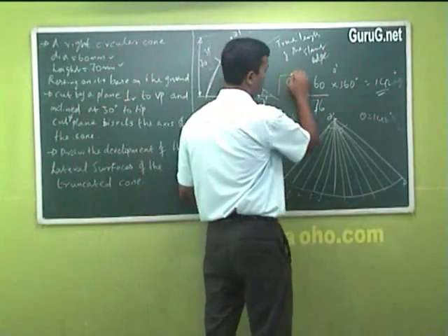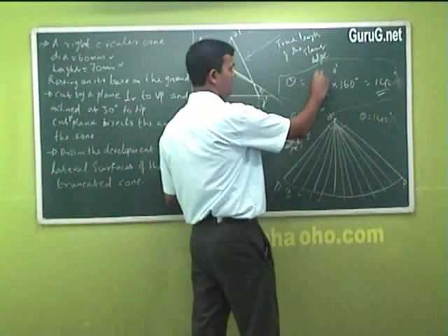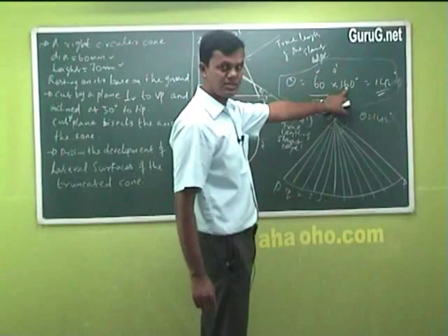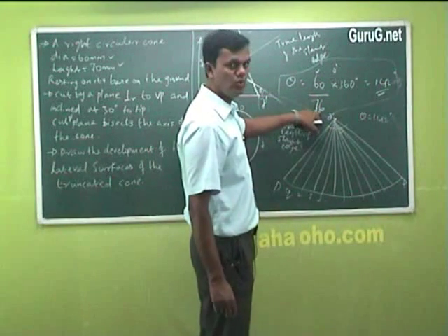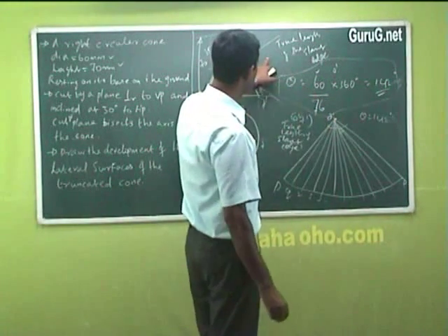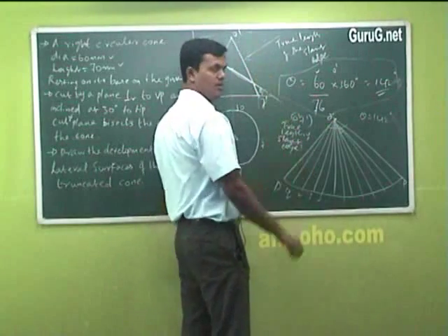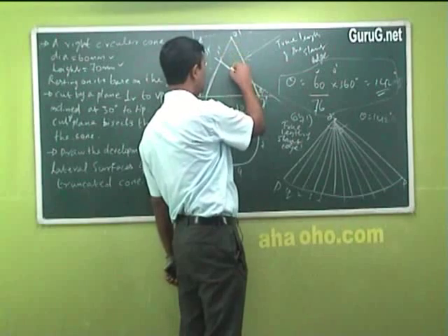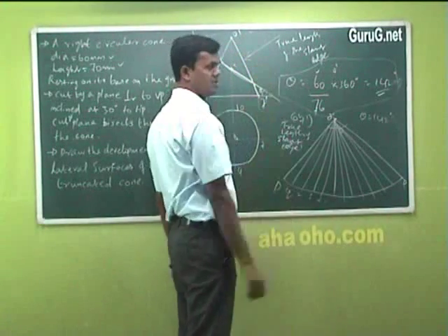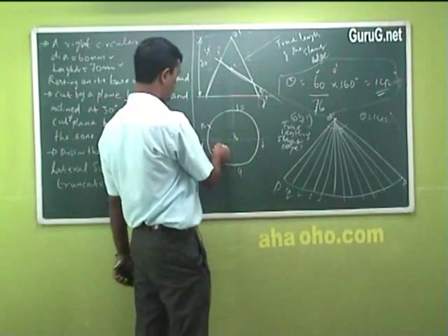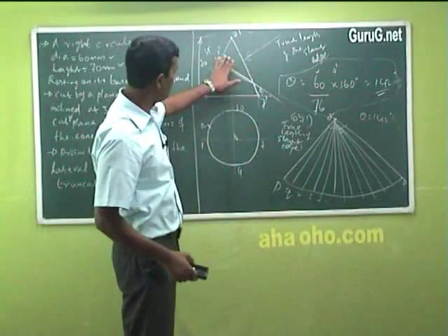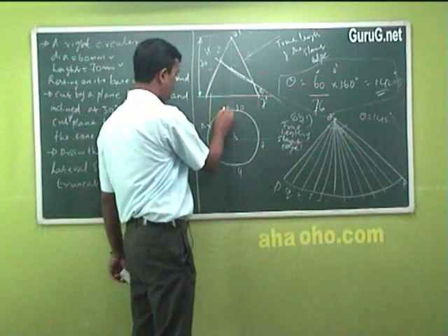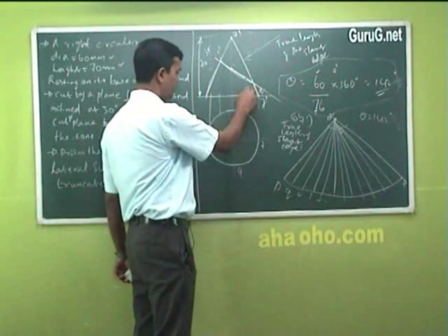And this formula, please remember it. It is nothing but your base circle diameter into 360 degrees divided by the true length of the slant edge from the front view. So for the cutting edges, 1 dash, 2 dash, 3 dash, whatever edges you have, actually you have more than 3 or 4, because everything you have to project to the top.